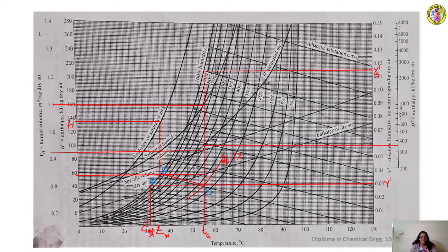So that is also obtained there. One more point is there. The straight line of the dry bulb temperature is meeting another line that is plotted for saturated humid volume. From that point you can read the humid volume of the saturated air, again on the y-axis to the left side. It is showing that the humid volume value is around 1.1 meter cube per kg dry air.